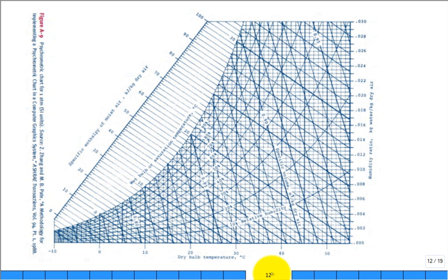This is the psychrometric chart. Did you already read about it? Struggle with it? Let's do a quick overview. What's on the x-axis? Dry bulb temperature. What's on the y-axis? Humidity ratio, but usually we put the y-axis on the left side, but you can put the y-axis on the right side. So right here is the y-axis on the right side: humidity ratio omega. So if somebody says I'm at this dry bulb temperature and at this humidity ratio, you find the point where it intersects.